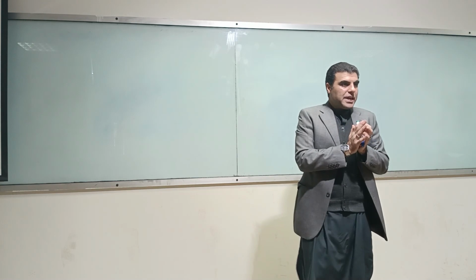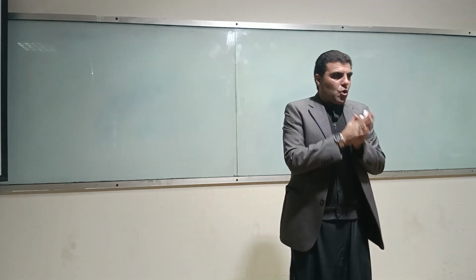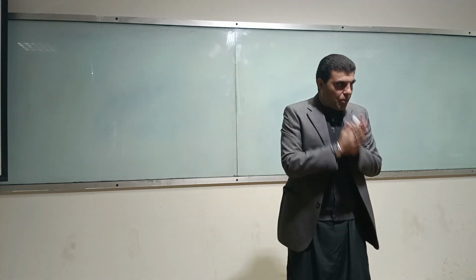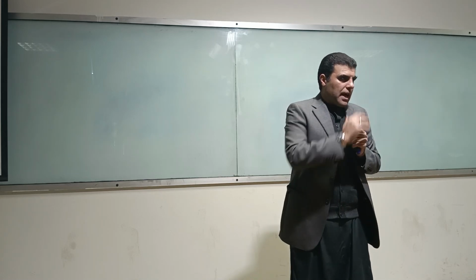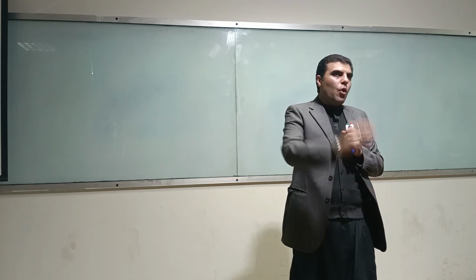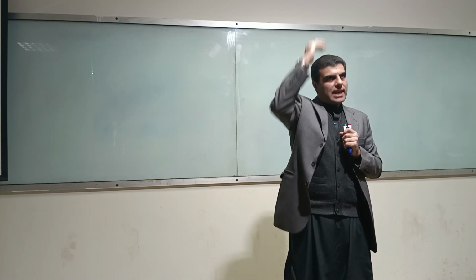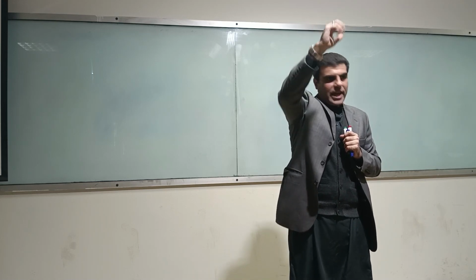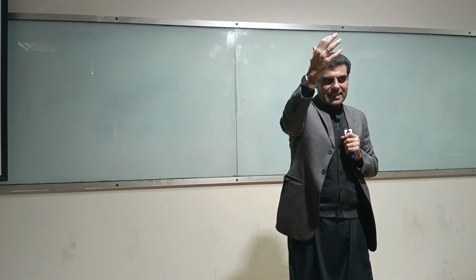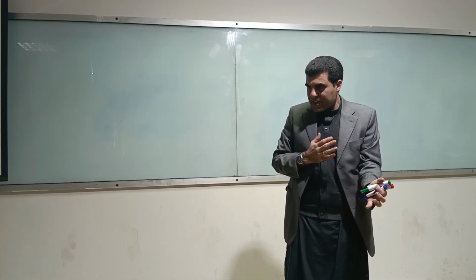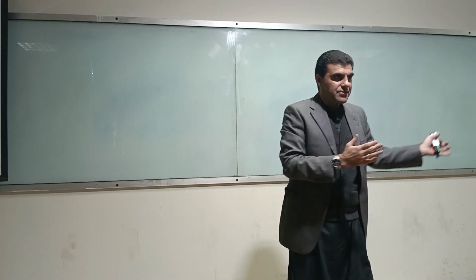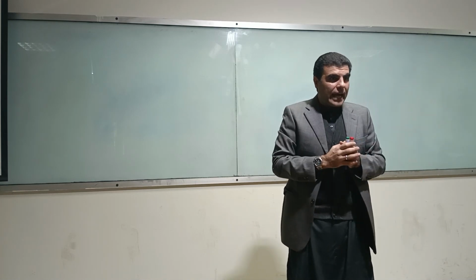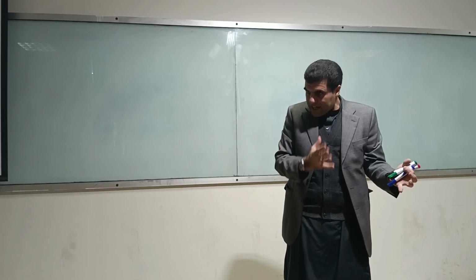And you, being a structure engineer, you must know what is an appropriate component which will transfer the load for you. So now, for example, you want a class on top of this room, okay? And this class, I've told you, would have students sitting there. So you've got live load, it has got desks, it has got a board, it might have some equipment, and so that is a sort of a dead load.